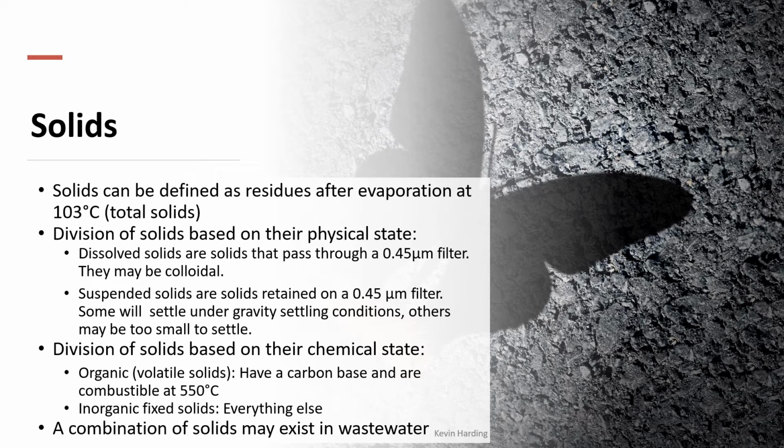Solids are also going to be an important part of wastewater or water quality, and the first thing that we are wanting to do is to evaporate the water sample at 103 degrees Celsius so that we have complete evaporation. We don't want to wait at 100 degrees Celsius. We want to make 100% sure that the sample is dry and how much residue is left over. What is the weight of the residue that's left over?